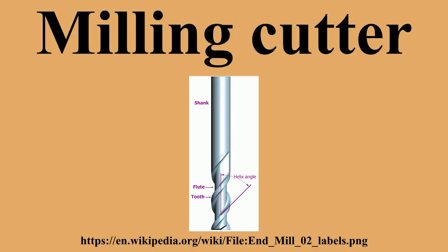For example, a 20 mm diameter cutter with a 2 mm radius corner. This usage is analogous to the term bullnose center, referring to lathe centers with truncated cones. In both cases, the silhouette is essentially a rectangle with its corners truncated.